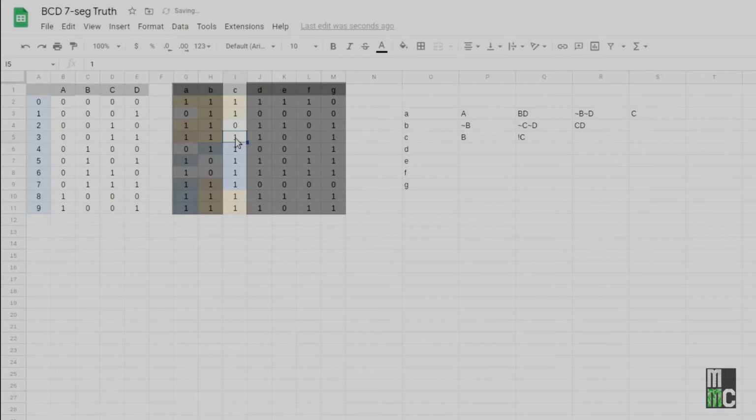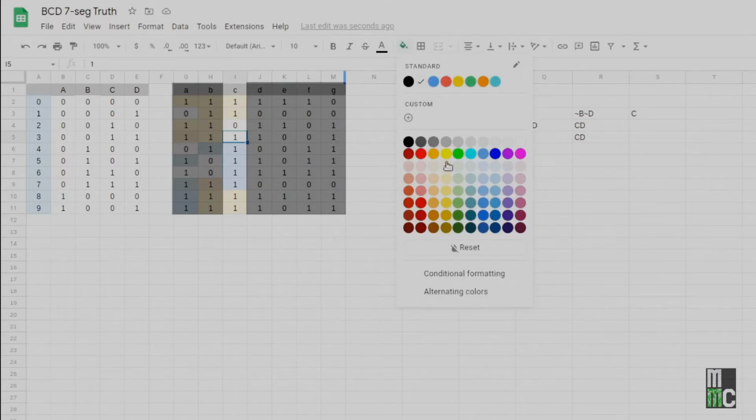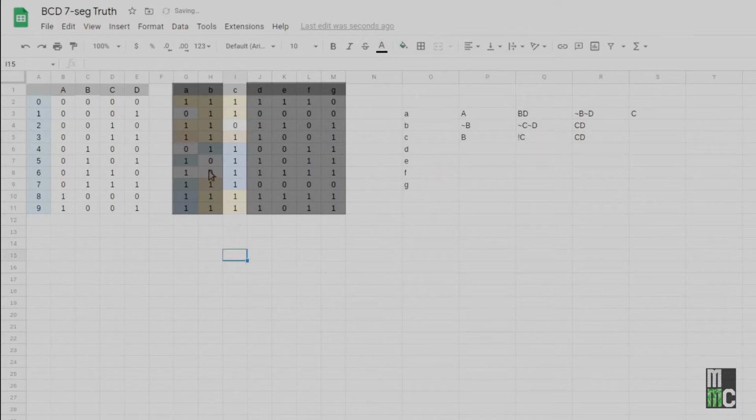But then my last case that I have is this one here. And the question is, how do I catch that? Well, it's only case where C and D is on are these 2 right here. And in both of those I have a 1. So by doing a C and D, I can get that too. And you'll notice the interesting thing is I already have that gate used here. So it won't be a new gate. I already have it exactly right there. So we're going to take this last one and we will make it orange. So I've got the C segment gate taken care of.